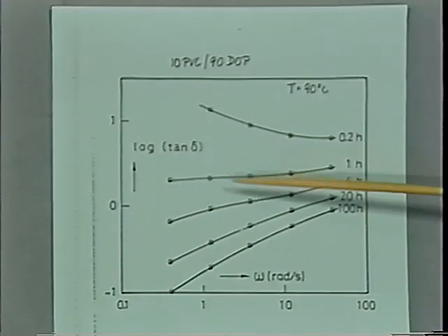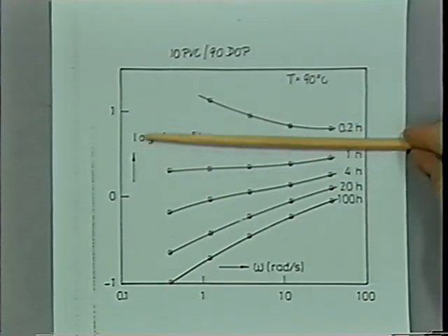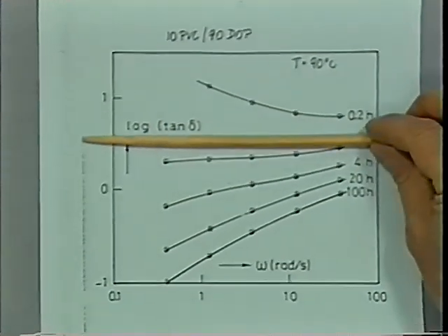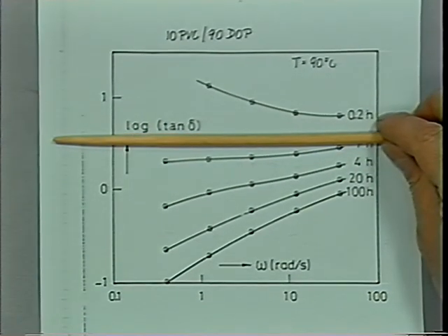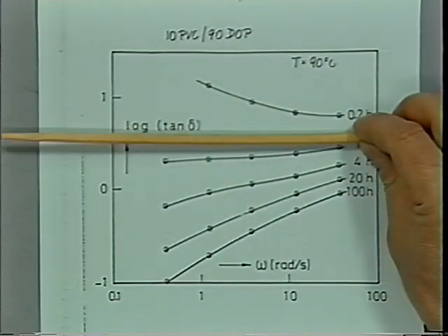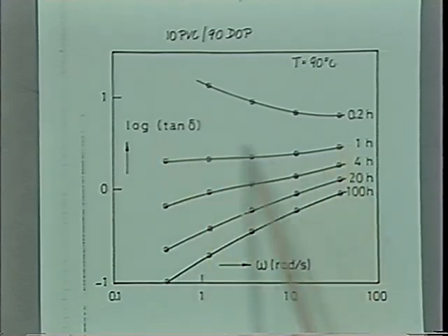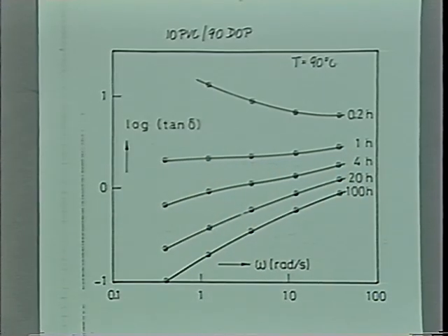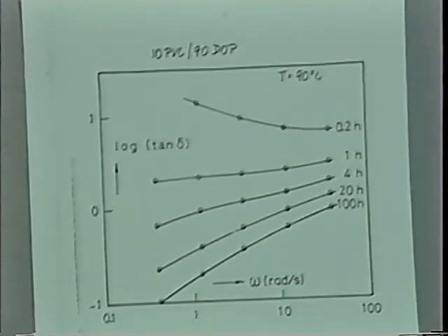He never looked at the gel point, I said, and here when you look at tan delta data now at various frequencies, you realize at 0.2 hours he was above, and at 1 hour he was beyond the gel point. And at 0.4 he also would have been before the gel point. So he didn't have any data where tan delta was completely flat. It doesn't matter because we know the type of evolution, and we can determine the gel point from this set